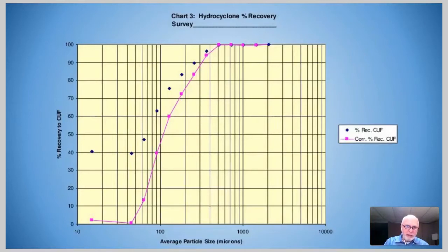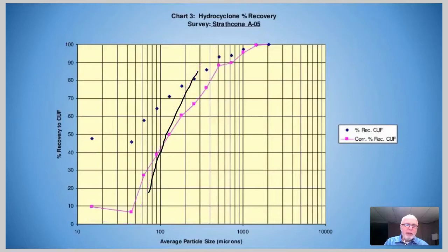We can characterize the sharpness of separation by the slope of this curve, which I've just imposed in. If we compare it to an old style cyclone, we can see that we've got significantly improved separation sharpness with newer design cyclones. Now this contributes, at least in a small way, to improved CSE. So we want to take advantage of that.